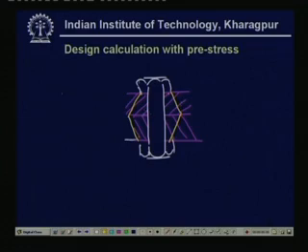Forget about the entire plate, and only take this amount and consider the stiffness based on this part. This also becomes complicated. Exact analysis will give very cumbersome results. Normally in design, you make use of some empirical relationship, that is, some experimental values of C.